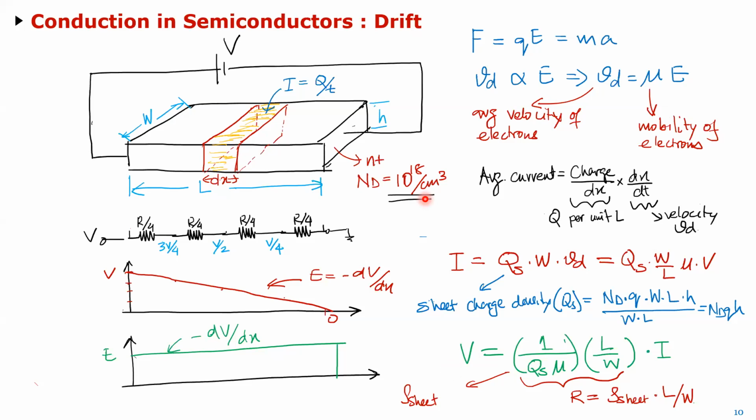That's one question. The second question is, in the lower technology nodes, the relationship between the mobility of electrons and holes is changing. There was a time when it was 1.5 to 2 times. Nowadays in 5 nanometer it is almost equal. It started at almost 4x, became 3x, and at 180 nanometer it is almost 2x, 2.5.